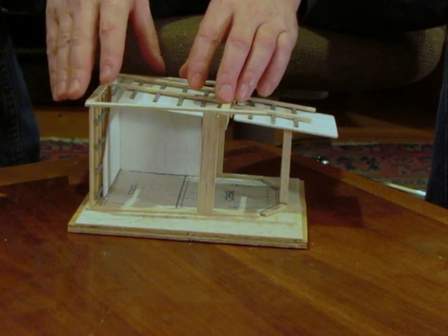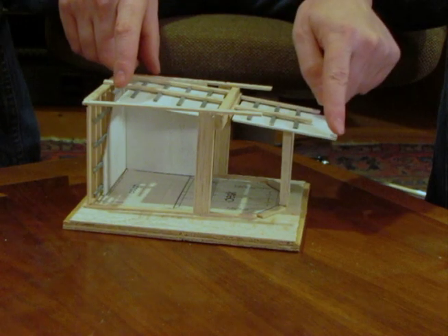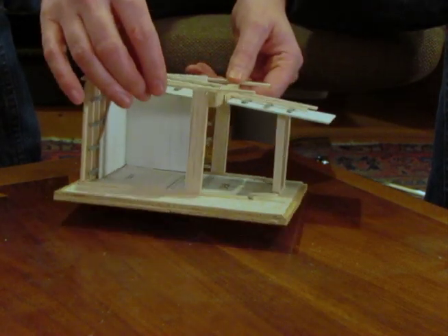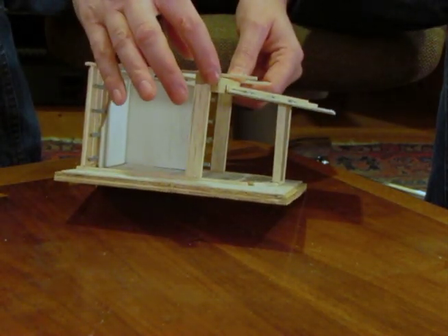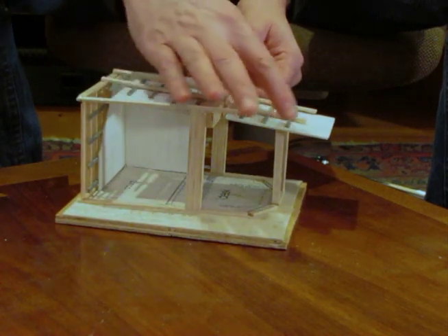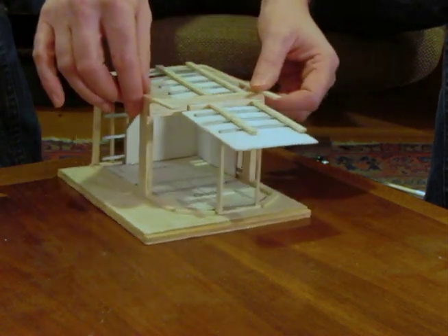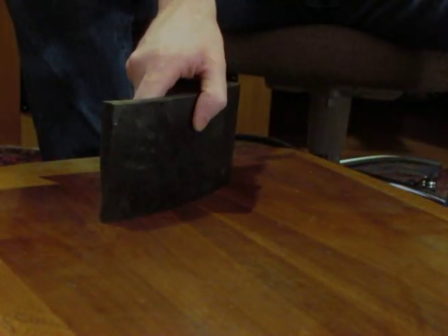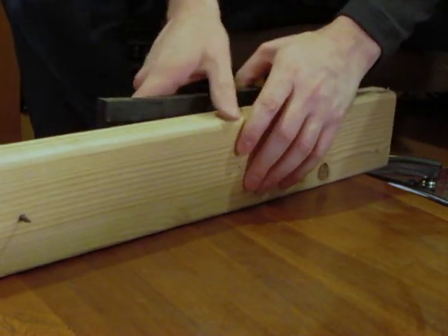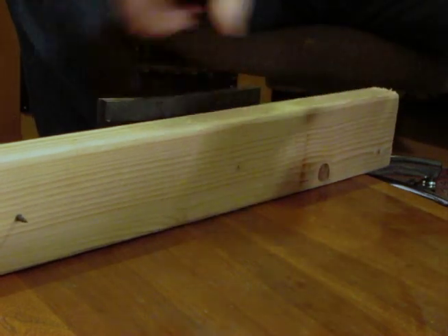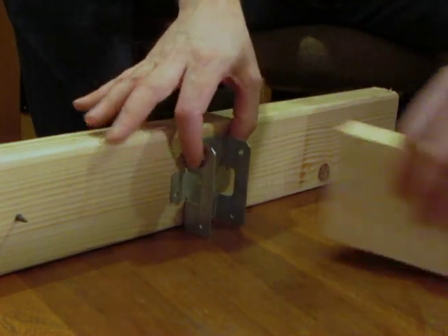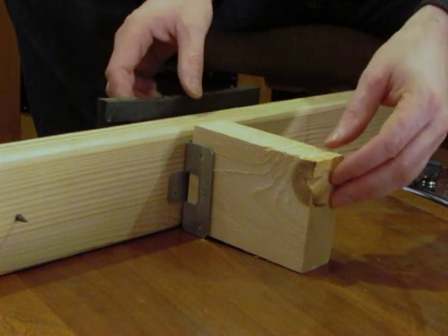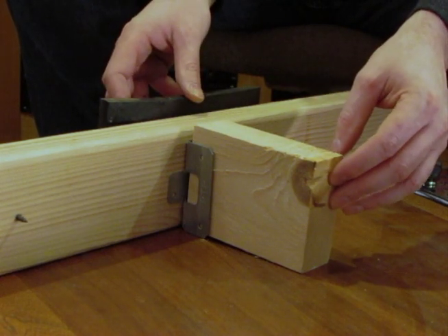Now we need to continue the ceiling support on the other side of the main beam. This is a bit tricky in that the ceiling needs to hang from the house joists and continue the same angle. The plan will be to attach a 2x4 to the main beam, but place a thick piece of neoprene between the 2x4s and the beam for the isolation. Then, using strong tie brackets, we can hang the ceiling frame from the joists.